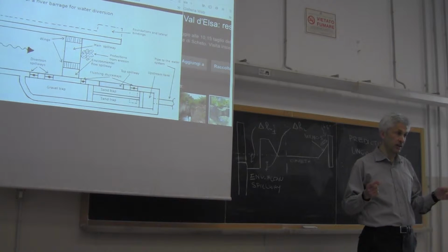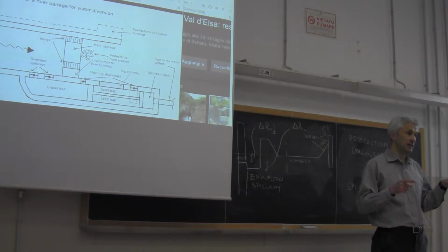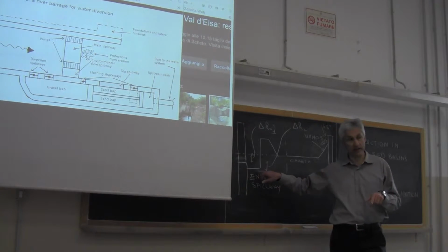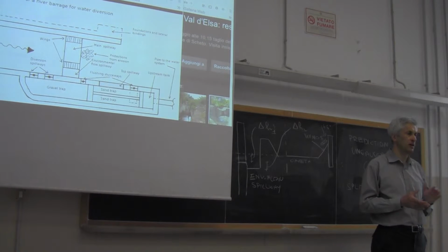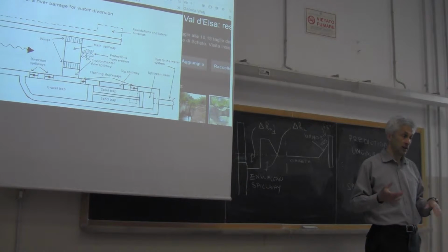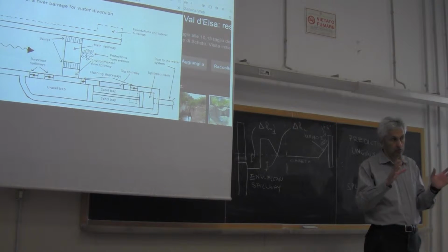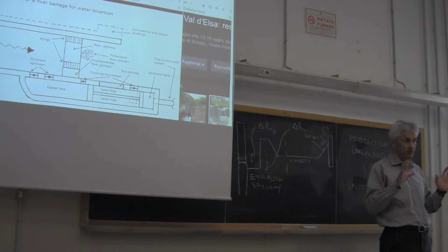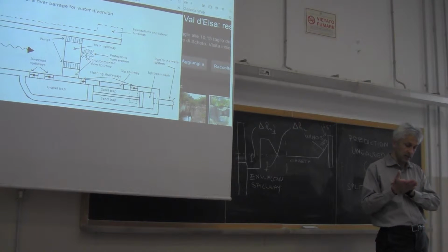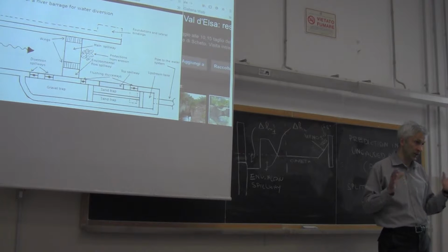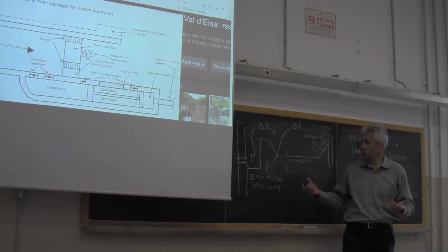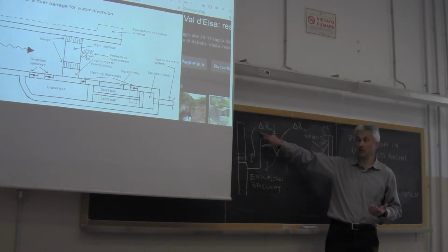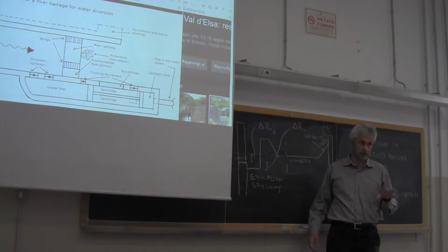And also, the regional laws and national laws tell you how to compute the environmental flow. The computation depends on the catchment behaviors, on the behaviors of the river, on the behavior of the fishes, etc. And you have to make sure that you refer to the correct law, because it's not your decision. Estimating the environmental flow is dictated by laws in general. In Italy for sure, but I would say that in any country. So it's not your decision. It's your decision instead to estimate these differences in elevations. And this is our next problem.